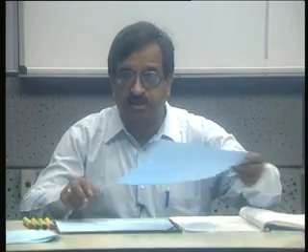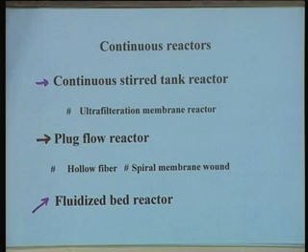Now, these are the three major classes of continuous reactors, but as a matter of fact in practice a number of hybrids of these reactor systems have been proposed by people, both in the case of CSTR as well as in the case of plug flow reactor. In fact, fluidized bed reactor itself is a hybrid between the two major classes, but even under CSTR a modification which has been proposed